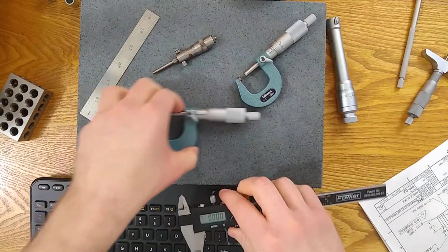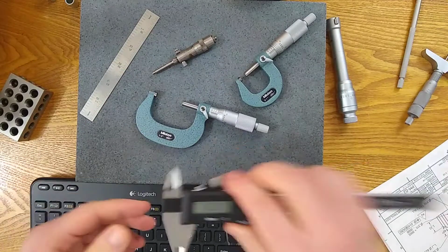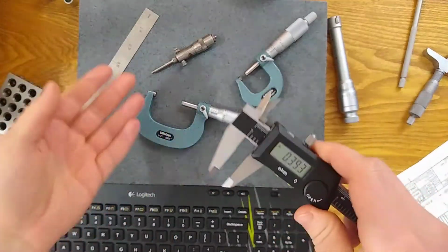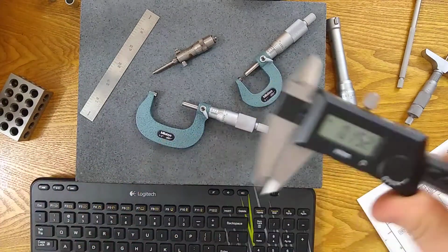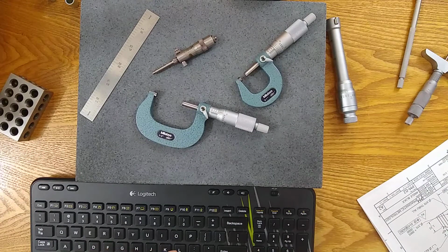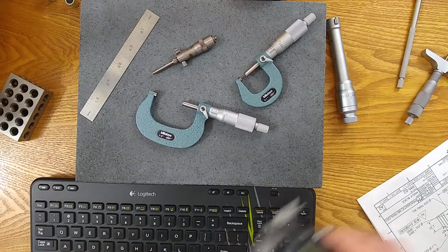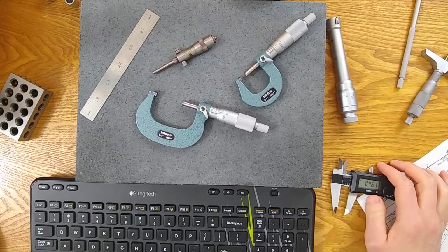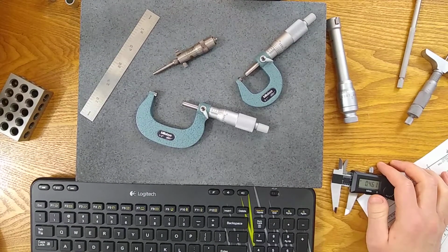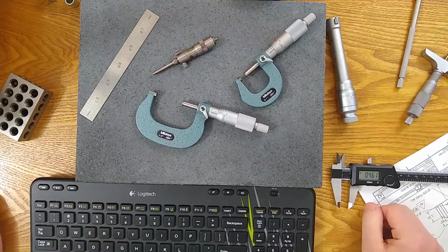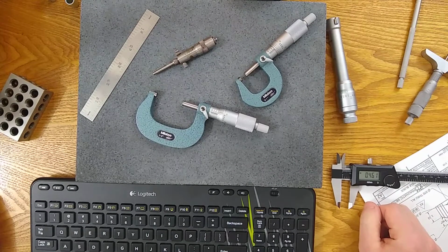So there might be situations where you could still maintain the accuracy that you need at a minimum. You're giving up a little bit of accuracy by changing, but you still get at a minimum what you need, and you can do it faster and still maintain the accuracy. So there's other situations too. Maybe you used the CMM and you thought, well, I need to use the CMM, and then you're like, oh, well, now that I went through all this trouble, actually I could have just done this on a hand tool or a surface plate and gotten the same confidence in my measurement.